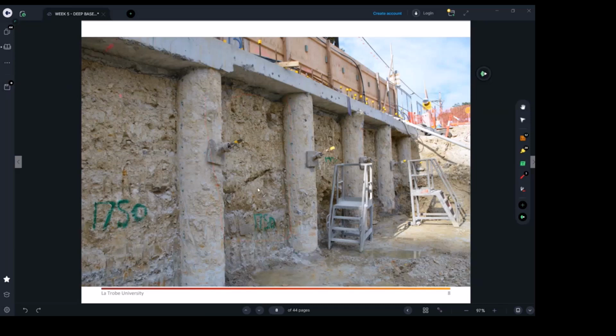Now, this may look fine for a car park. The architects are not worried about the look. However, you can't have this in a habitable area, maybe in a basement or some shopping centers. If there is no room architecturally to build such a big pile, a 900 diameter pile, then the challenge is we have to think about alternatives. Maybe we go with a solid wall, 200, 250 thick, all the way from this point to the end. Sometimes you are limited architecturally by what the architect wants.